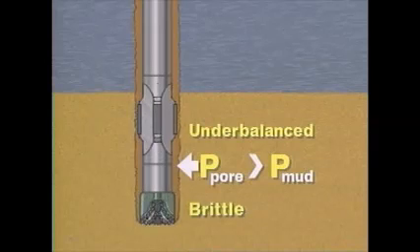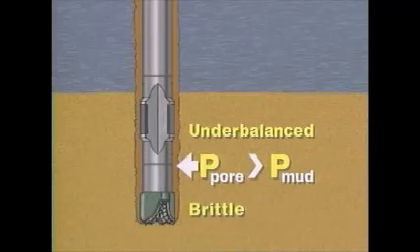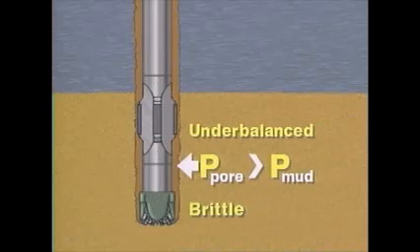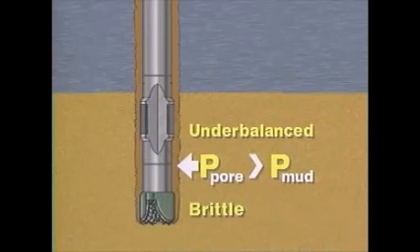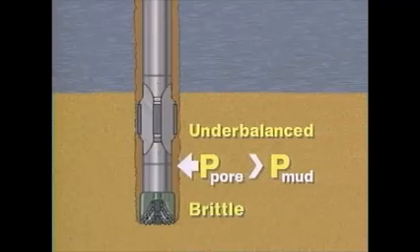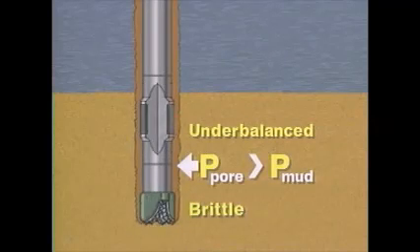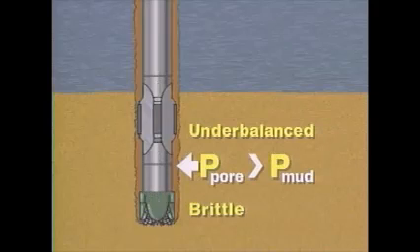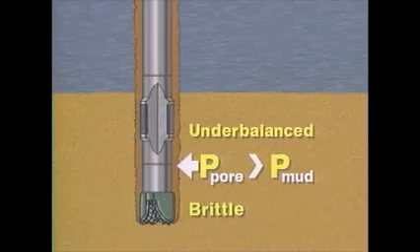Because the rock surface is in tension, it virtually explodes under the compressive loads of the bit. There is very little regrinding of already drilled cuttings. This helps attain very high rates of penetration, and is a major reason why air or foam drilling tends to give higher penetration rates than conventional overbalanced drilling using a weighted mud.